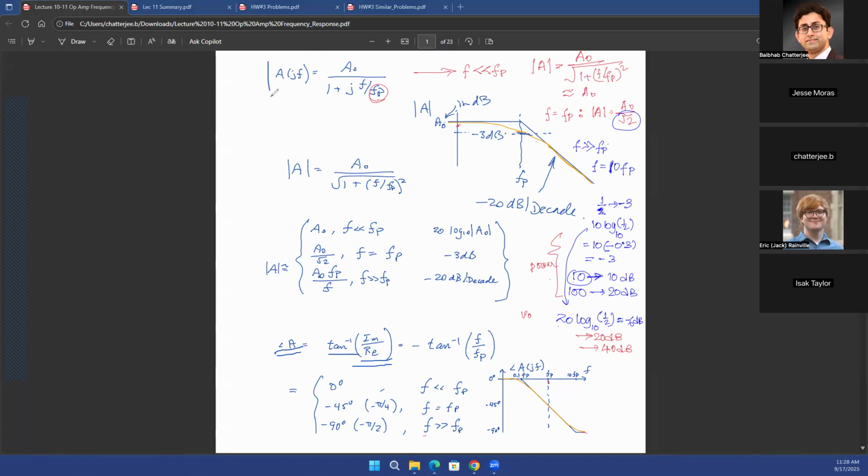Now, if you go back to the original equation, which is the same as the equation that we had written for the low pass filter, remember that there the gain was 1 divided by 1 plus SRC. And what was 1? 1 was the zero frequency gain. The numerator was the gain at zero frequency. So instead of 1, if you have a zero frequency gain which is higher than 1, that becomes your numerator, which is A naught.